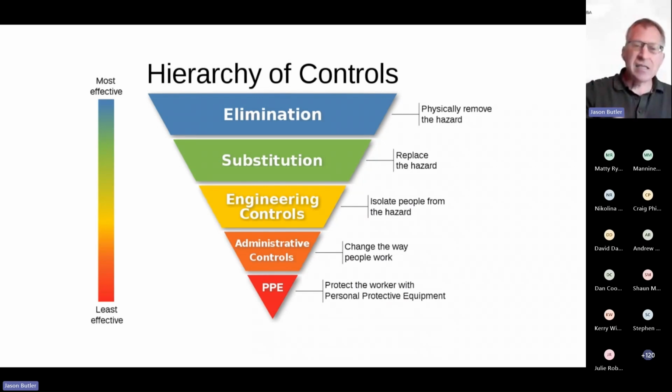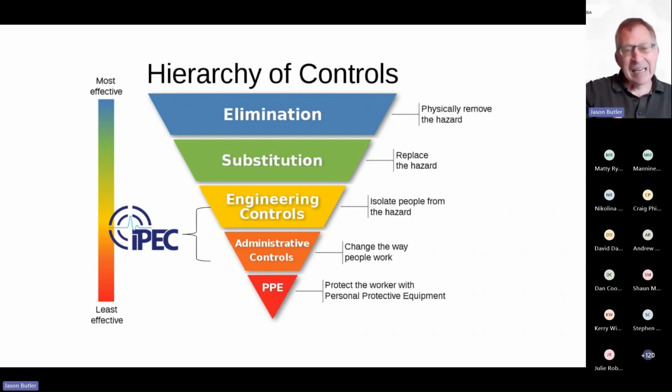And where PD kind of sits is at the engineering control and the administrative control, because ideally, it gives you a way of understanding what is going on without being in front of the hazard, because PD is detectable whilst it's live, but non-intrusively. So you are away from the hazard. But even with all this technology and all the things you're going to learn today, there's still a residual risk. And going with that adage of going home safe, no matter what the residual risk is, your PPE, which is the last line of defense, should always be on.